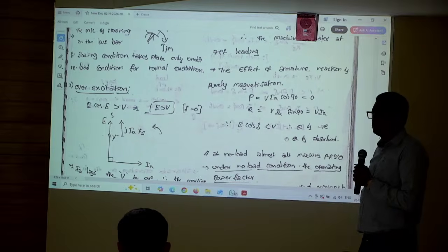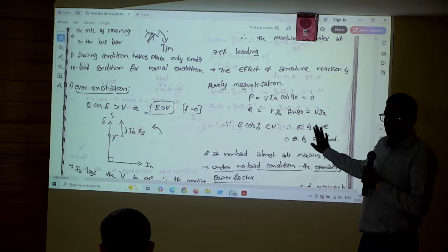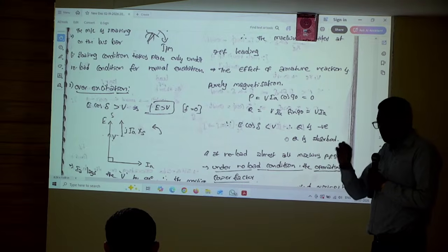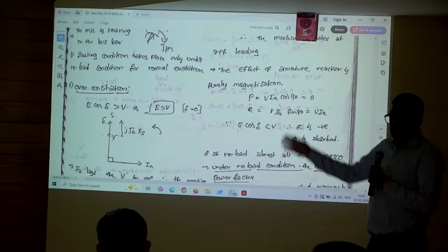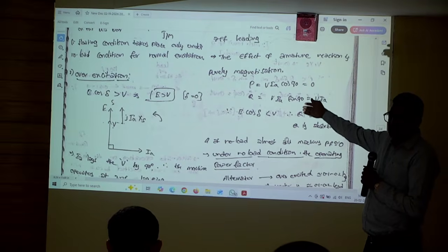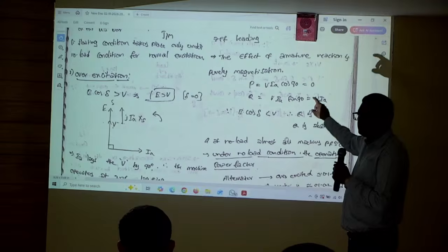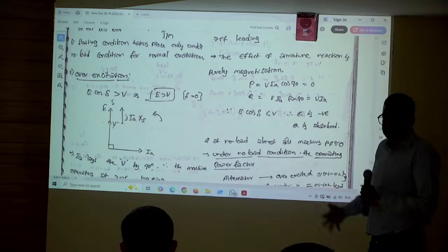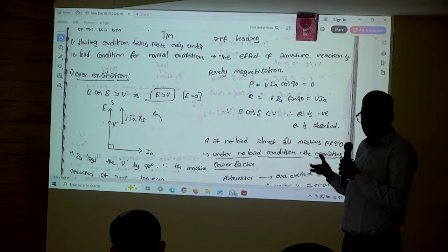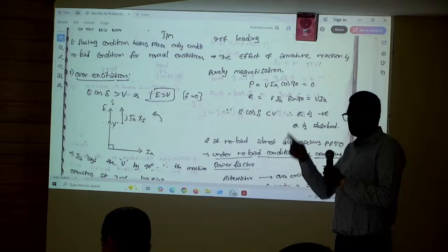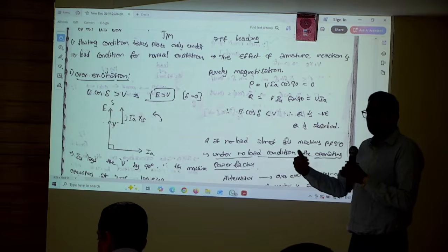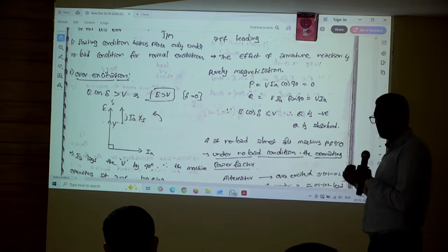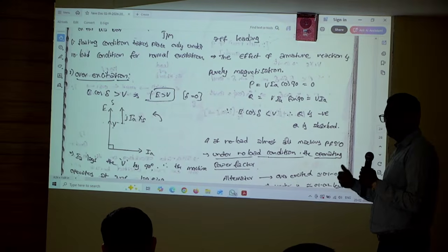Okay, for over excitation, E cos delta is greater than V. Taking delta as 0, we are assuming, everywhere I noted as assuming load angle is 0, but practically E at an angle delta exists. In the early equivalent circuit, terminal voltage V at an angle 0 I consider, because that is where our analysis starts. Once the alternator is giving reference voltage Vm sin omega t, it means at no phase, at 0. Entire electrical engineering starts from there: power system analysis, circuit analysis and all transformations, and we start from there.